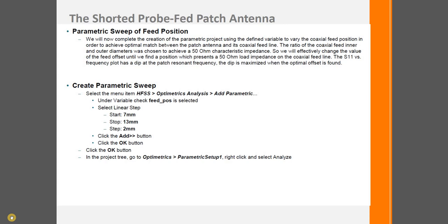The S11 with the frequency plot can show us where the resonance frequency of this patch is, and the dip is maximized when the optimal offset is found.